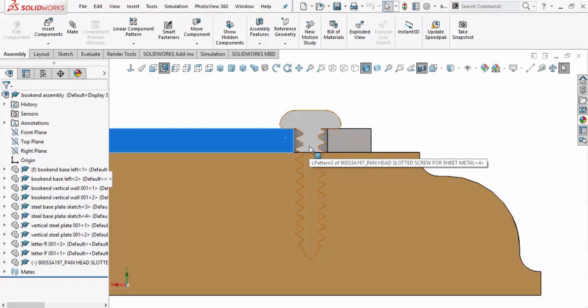Yeah, it may be a little bigger, but I'm not going to go buy a 9/64 drill bit so I can put that in. They're kind of hard to find. So 3/16 definitely is one I can find. Again, we're designing and manufacturing to our tooling. Plus, if I wanted to, I could put epoxy down in that hole and fill up that gap, and it makes it even stronger.